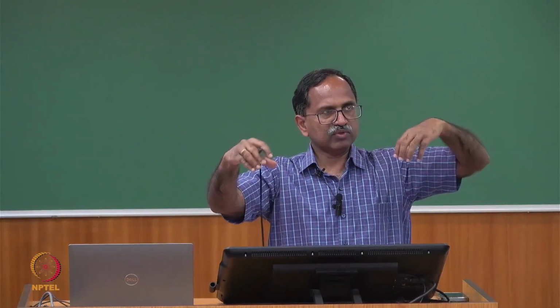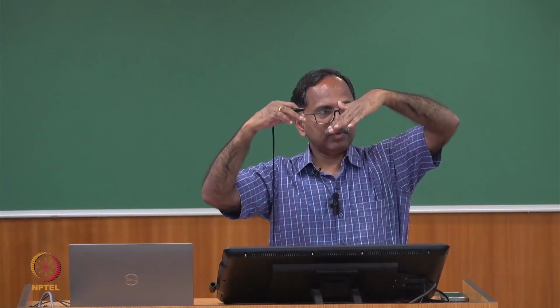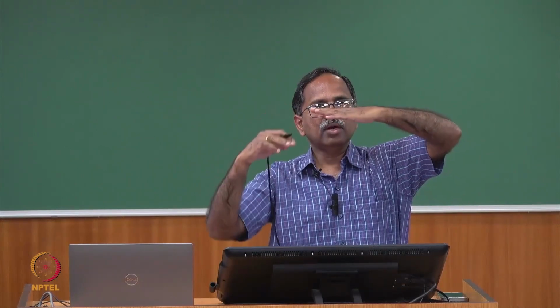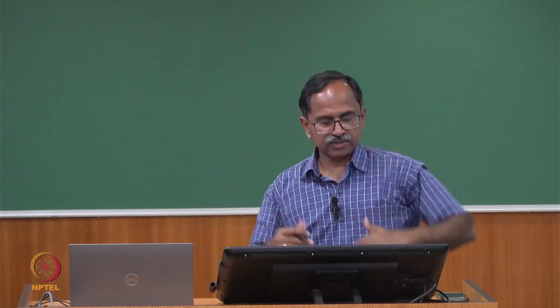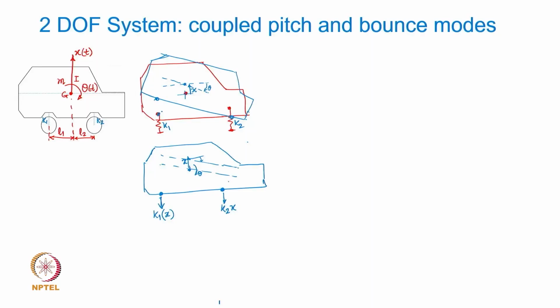Both of the two spring positions are going to get stretched, but you see the other motion as well, both x and theta are simultaneously happening. Now, if it tilts like this, then the tilt motion is going to extend the spring position or the spring end further up, if theta is assumed clockwise positive.